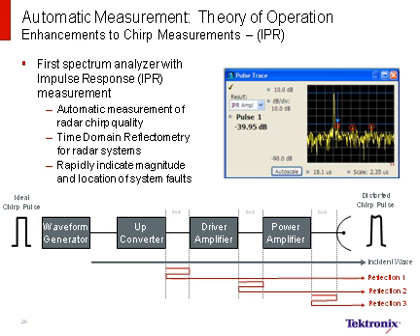There's been a recent enhancement added to assess linear chirps, and this is the impulse response measurement, or the time side lobe measurement. You can think of each of the discontinuities that exist in a transmitter, from the generation of the signal, up converter, driver amplifier, power amplifier, and even at the antenna. If there is an imperfect match at any of those junctions, you get a reflected signal, an attenuated, reflected, and time-delayed signal. This is called an impulse response, a triple return, or time side lobe. We have automated the ability to see these time side lobes by convolving the signal of interest using a single port measurement.